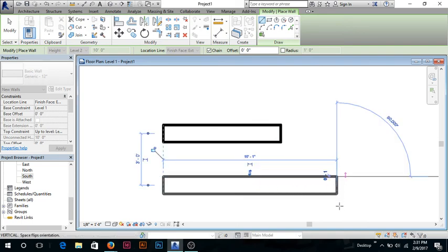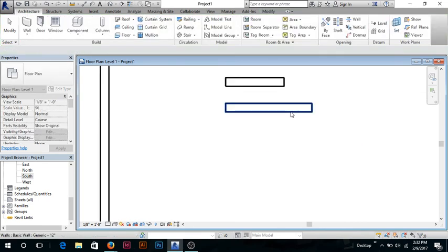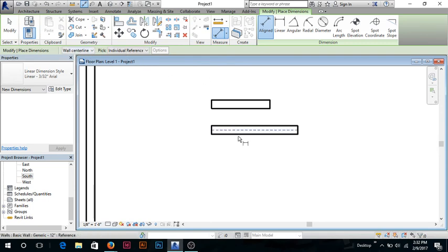So when I draw a wall and I go to draw another wall, it kind of cuts it in, or you can flip it back and forth. So that's one thing I would always keep in mind, because even when you dimension, you get that same kind of option, right? So wall center line, and you can say no, center or wall faces. I want the wall faces. So every time I dimension it, it kind of automatically snaps into the exterior instead of the interior, right? Or the middle, sorry. So the same thing with that.